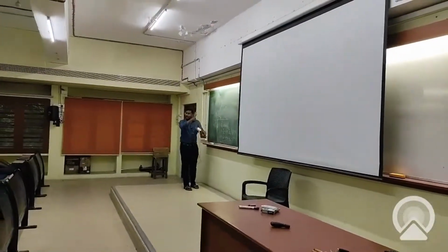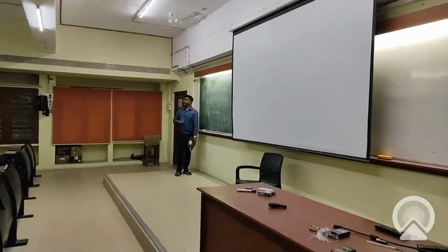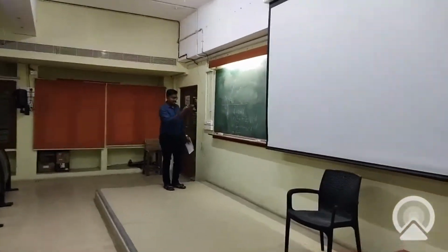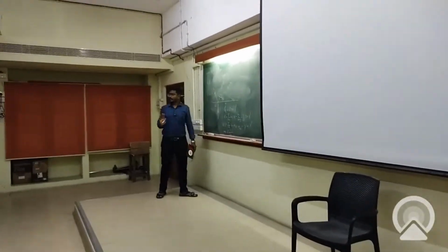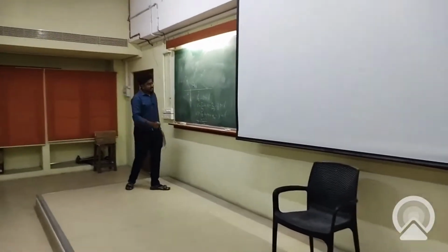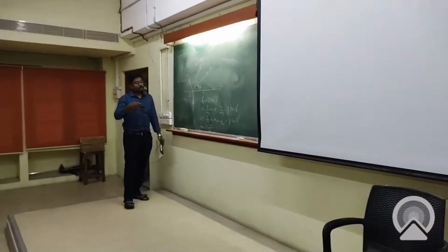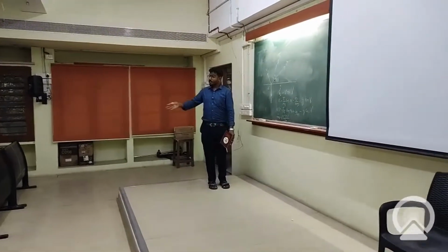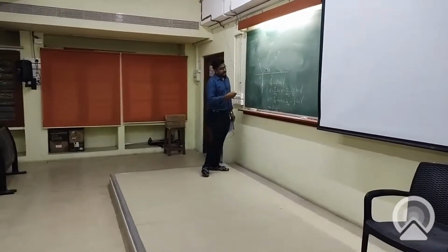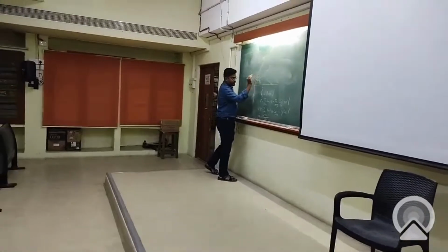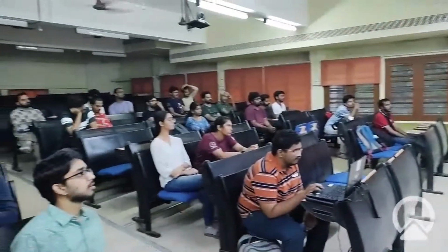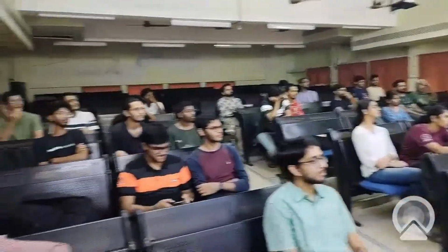I'm not telling that this is the streamlined functional dynamics. In this, we have the states h, V, gamma, and m. These are the states. What is the control? Obviously, it is a control along with the state. What is the control? It is nothing but this alpha. Or otherwise, alpha plus gamma is nothing but the pitch angle, right?